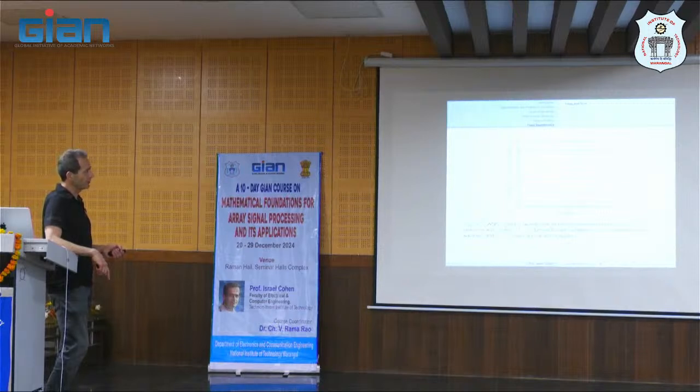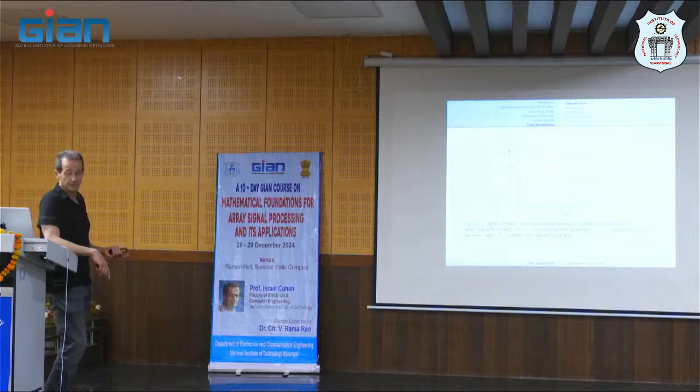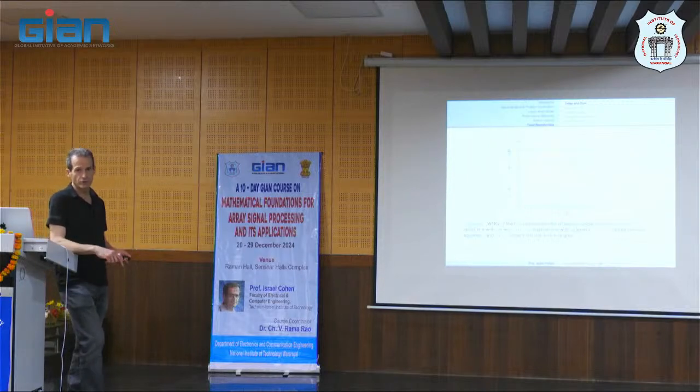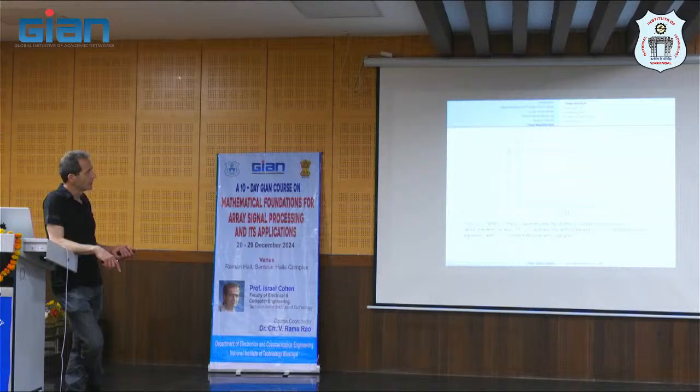We use the delay-and-sum beamformer with 2 sensors, 4 sensors, 6 sensors, and 8 sensors. The more sensors we use, the more the white noise gain increases, because the white noise gain is just the gain in signal to noise ratio.